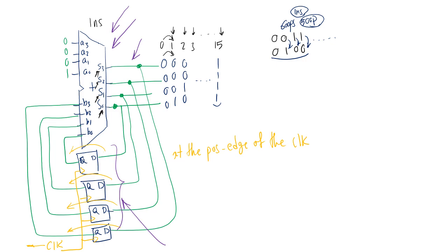Imagine that I wanted to design a counter that only counts the odd numbers, going from 1 to 3 to 5 to 7 and so on. All you need to do is put a 2 here and initialize with a 1, and then you're just jumping up by 2, right? That's just an adder. Instead of this entire adder, I could have any kind of combinational logic, and we're going to see those different kinds of combinational logic in the next lecture.